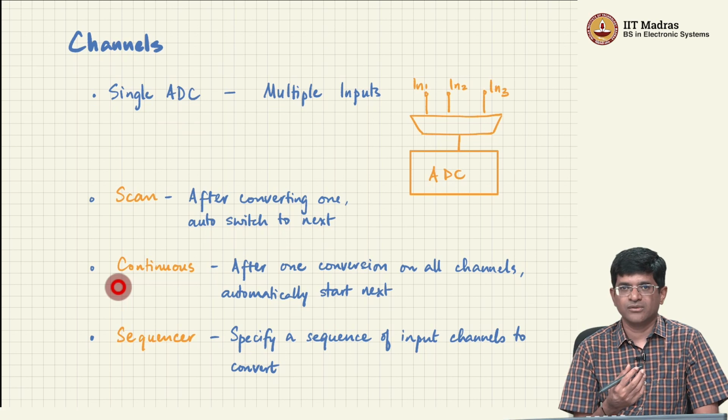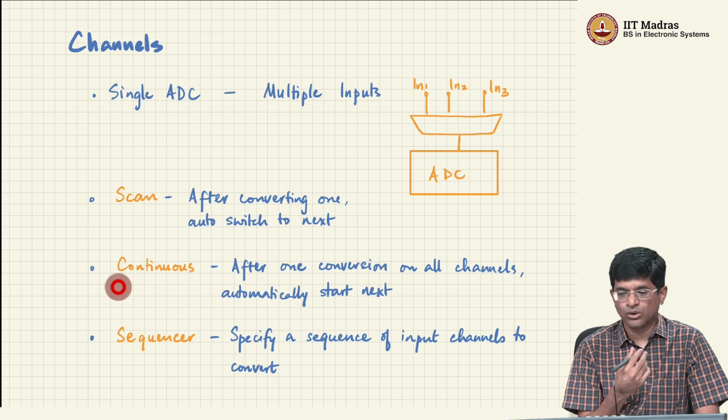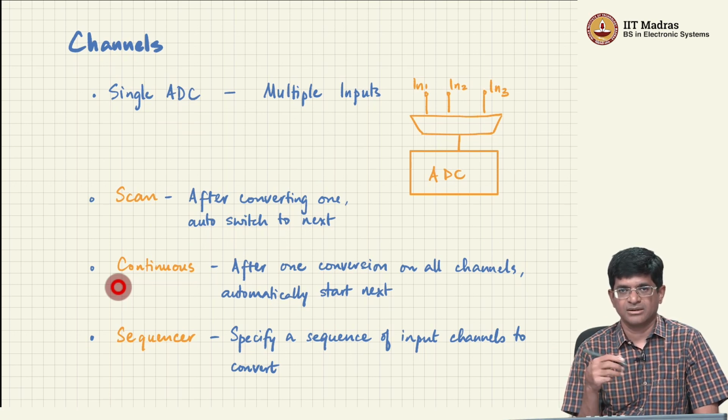But I might also have what's called just event based sampling. Maybe once in every second I just want to see what the temperature is like. That's not really enough data to find out the fine grained variations in temperature, but maybe it's good enough for what I have in mind. So if that is the case, then I don't do continuous sampling, I just do event based sampling. Maybe I set an event which wakes up my microcontroller once every second or once every minute, looks around, samples all my sensors, sends them off somewhere and then goes back to sleep.